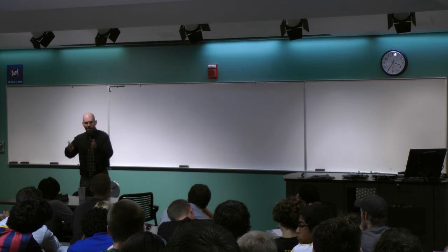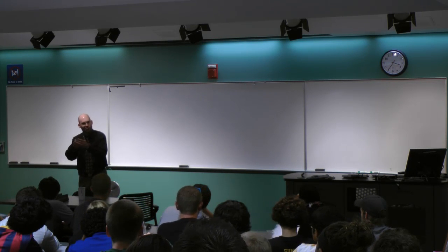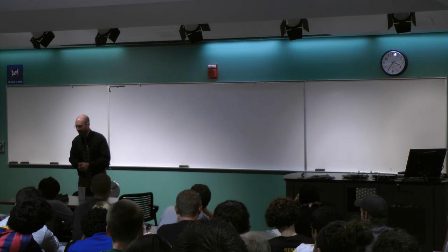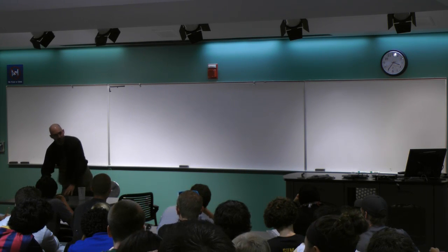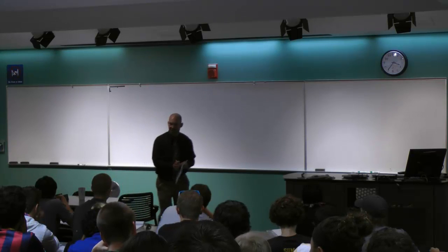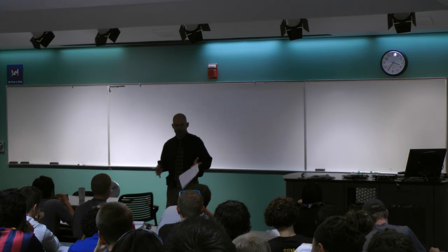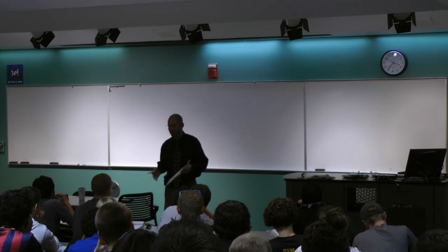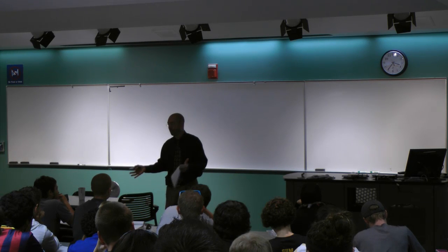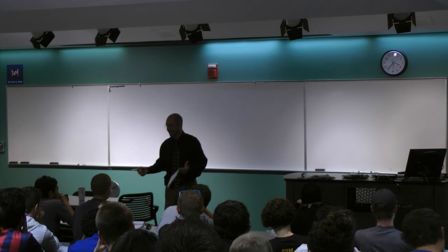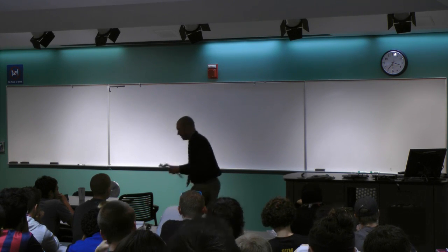But you'll realize, hey, I can apply this really mathematical method to solving it, and it's almost like magic, it just takes care of the trigonometry for you, which is actually kind of nice. And one of the best ways to illustrate that is with a two-link robot problem. Because you guys, even for homework this week, are working on two-link robots, trying to solve for the angles, using laws of sines and cosines and doing all this trig. You can go back and do the same problems with vector addition, and the trig just falls out like magic. It's kind of neat. So let's take a look at that.